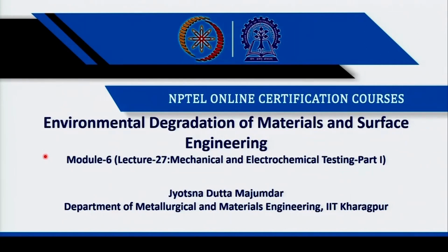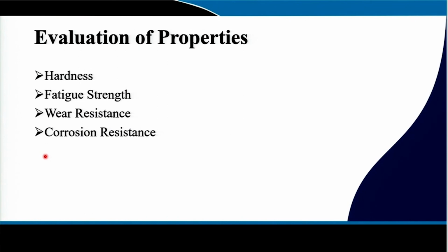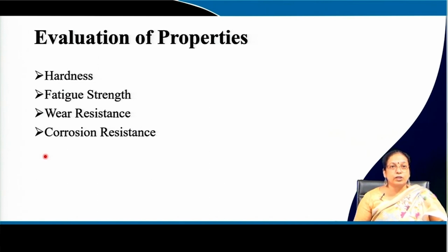Those are hardness or micro hardness, then wear and also fatigue property. So, now if you quickly go through the ways by which you can evaluate those properties, certainly none of them can be evaluated by non-destructive testing as we discussed in the last class. So, you have to go for destructive testing, and in most cases you have to follow the simulated conditions of those particular degradations or properties where the component needs to be used, but usually we just use a few standard evaluation protocols which are near similar to simulated conditions, because if you would like to measure those properties in simulated condition, you have to have the specific environment and specific equipment where you have to do the testing.